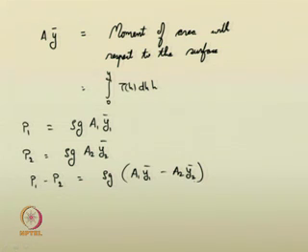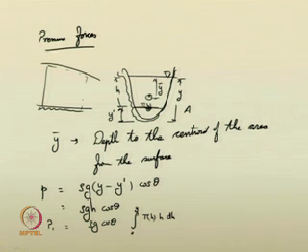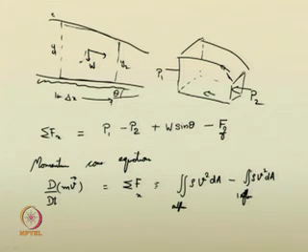That is fine. Now, the next quantity in the net forces. The net force includes the pressure quantity which we have already suggested, P 1 and P 2. Then W sin theta, what is the component of the weight? In this control volume, the weight is density into area into del x, that should give you the weight. Then sin theta gives you the component in the x direction.